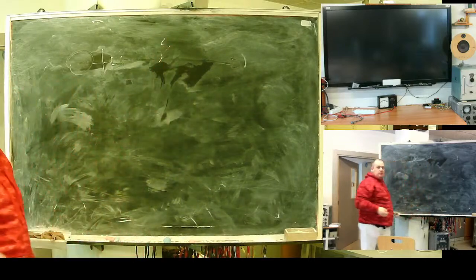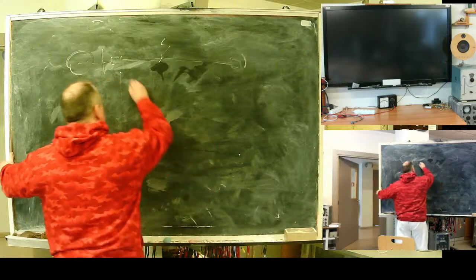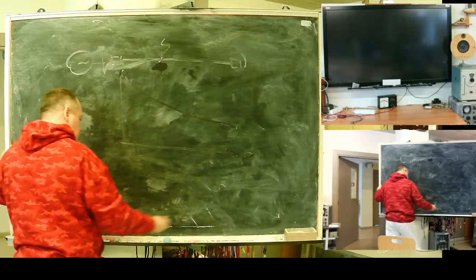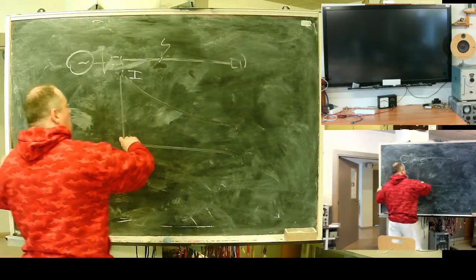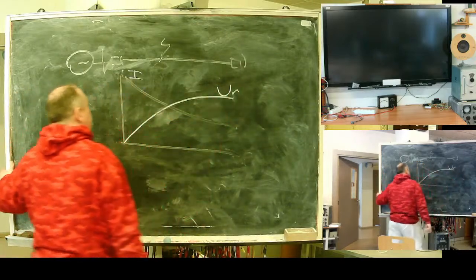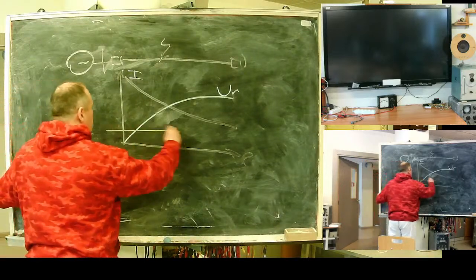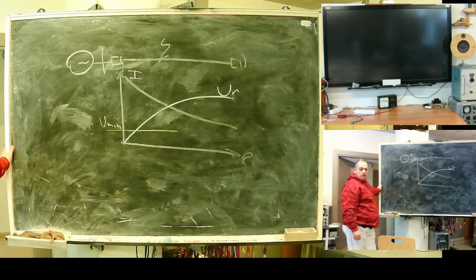Fault. What's the problem of blind zone? Distance to fault. Why it's not right? Current. Voltage available to relay. There always is a minimum voltage for relay to calculate resistance. If voltage is less, relay can't calculate anything.